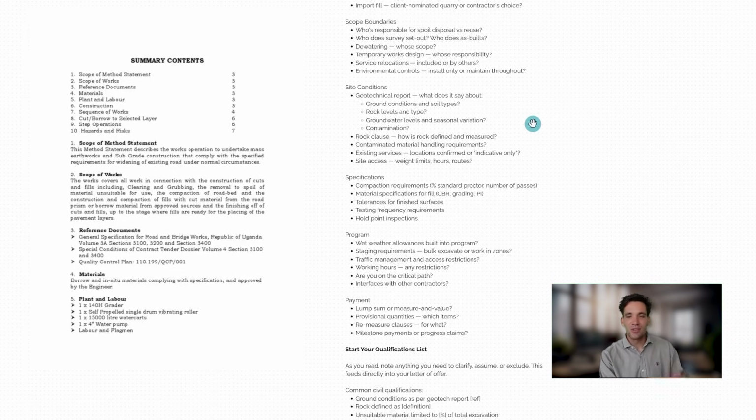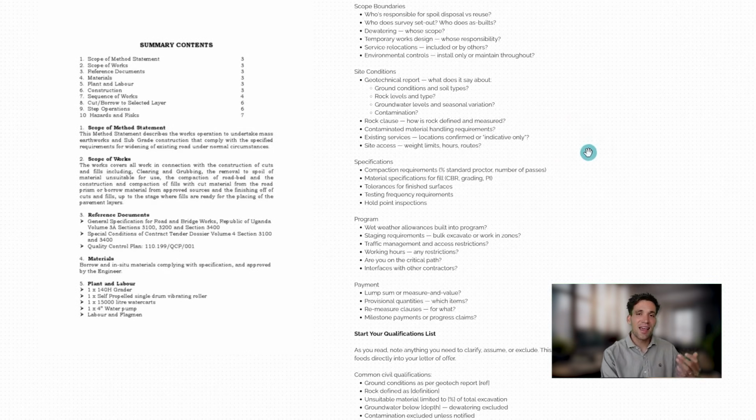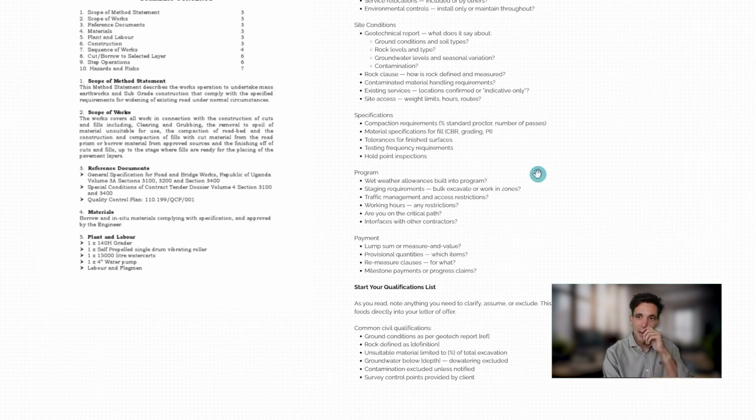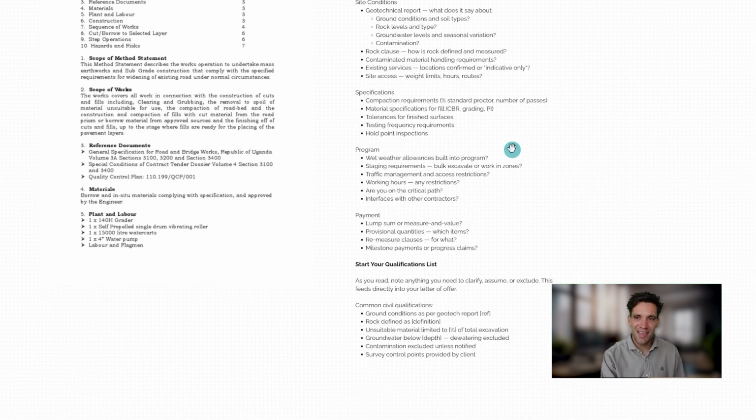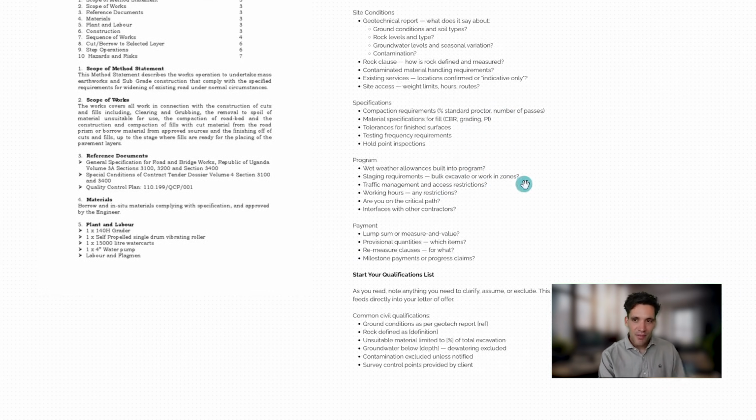Site conditions, look, I'm not a civil engineer, I'm actually an electrical engineer, but obviously excavating through rock is slower than excavating through fill. Groundwater, these sorts of things. Contaminated material, again, it's a huge cost. Existing services, I already mentioned that. Specifications, what are the compaction requirements? Is it 98%? Is it 95%? Material specs, testing frequencies.